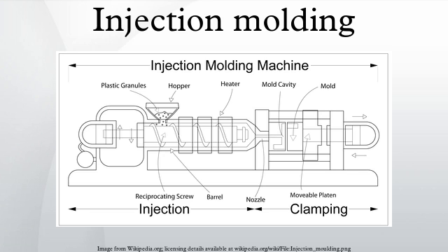Tool materials. Tool steel or beryllium copper are often used. Mild steel, aluminum, nickel or epoxy are suitable only for prototype or very short production runs. Modern hard aluminum, with proper mold design, can easily make molds capable of 100,000 or more part life with proper mold maintenance. Machining. Molds are built through 2 main methods.